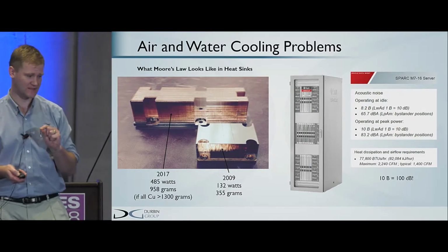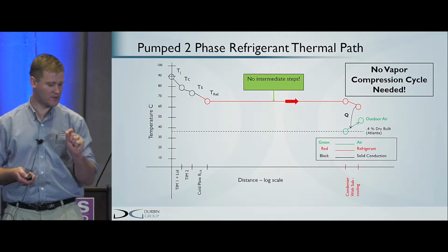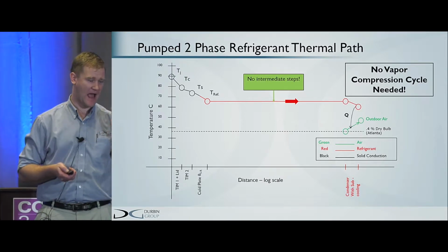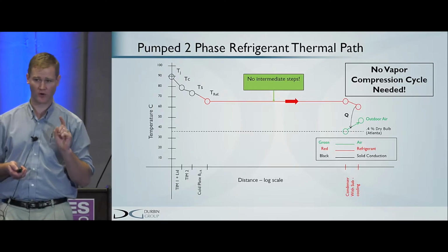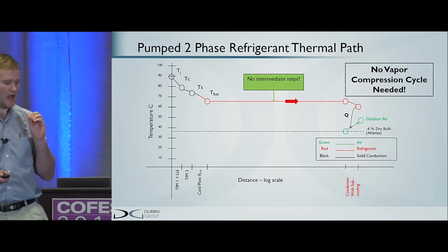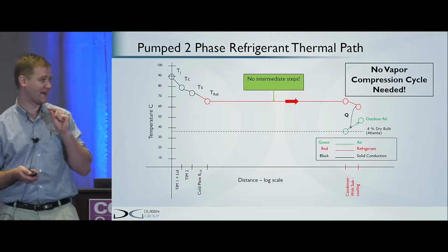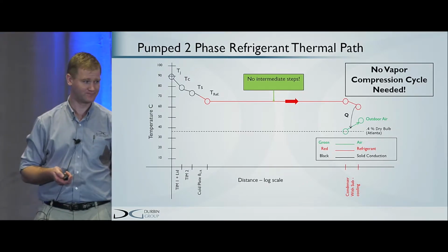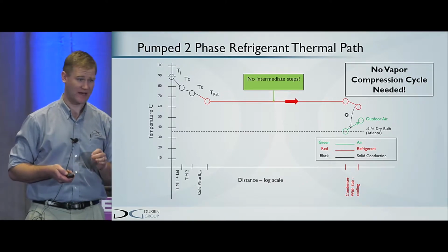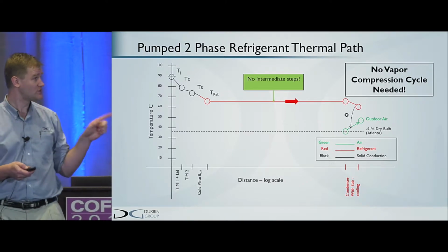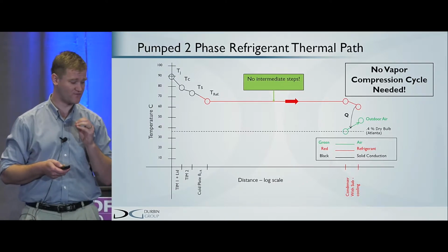So what do we do about this? What we are doing is skipping the single-phase heat transfer fluid and going directly to a two-phase isothermal working fluid that removes heat by, get this, evaporation. And that fluid is a refrigerant. The reason to do this is because that fluid is very efficient.